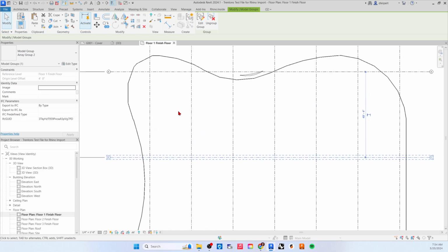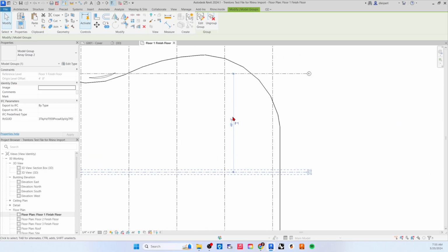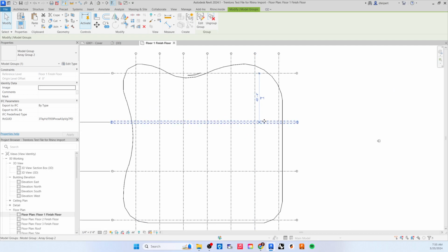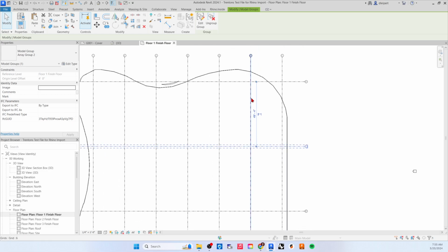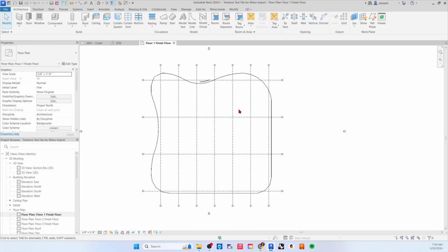If I click on this, I can see that I have 48, 49 feet roughly. So if I wanted to figure out how deep those beams need to be that carry the other beams that are going the 24-foot span, in order to carry all those beams going the other way, it's going to be pretty much 49 feet times 12 to get its inches, plus another 4 inches. Divide that number by 20, and that's about how deep those long beams are going to need to be between these two, right? This length. And that's going to define the lowest points in my livable space, from floor to bottom of those beams.